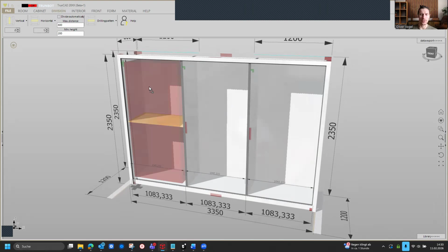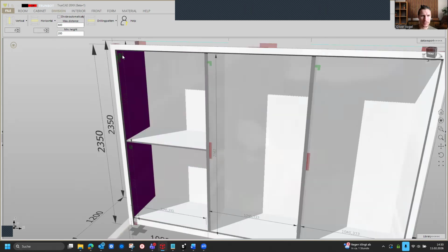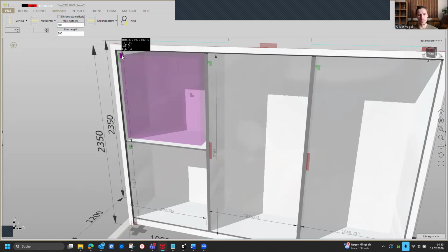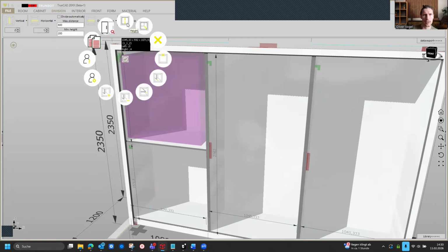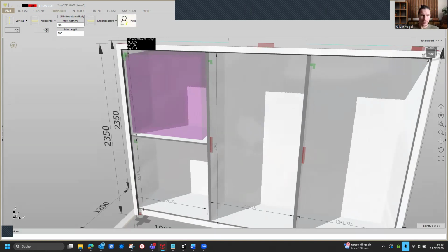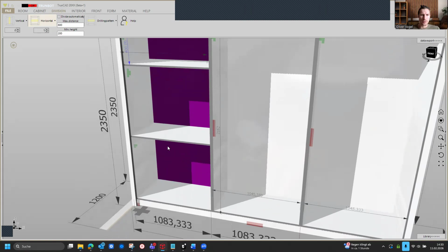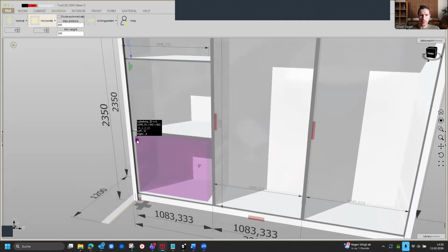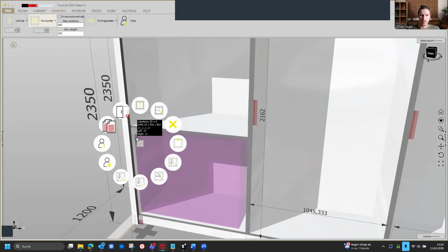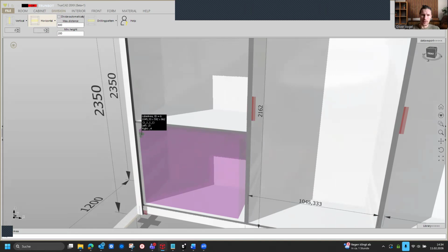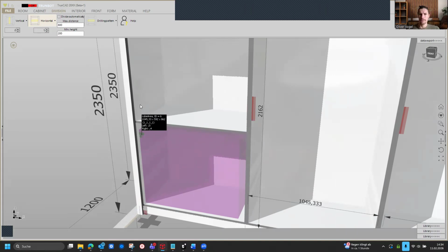We add here a horizontal, and we go on a smart click for the horizontal for this top left area. We click on here and we change the height to 400 millimeter. The same again, we drag and drop here one more horizontal, and we go on a smart click for this area. The circle menu is opening, and we change the height to 400 millimeter and confirming it with enter.